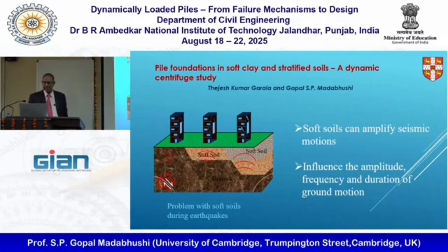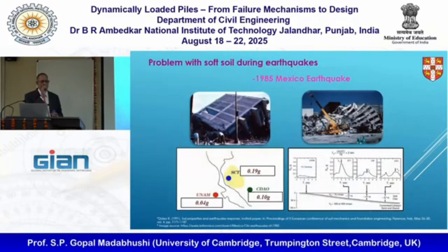So this is work Tejesh Garala has done. He is a new assistant professor at IIT Madras, and when he started, he came to look at piles in soft soils. All kinds of soft soils can amplify the seismic motion, and they are influenced by the amplitude, frequency, and duration of the ground motion. That's what we want to look at. And there are plenty of examples where soft soils caused trouble in the past.